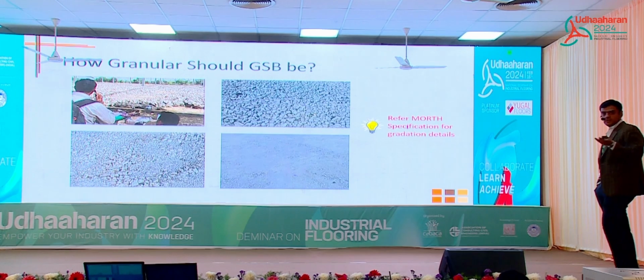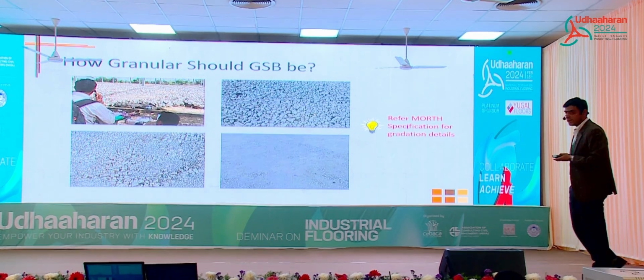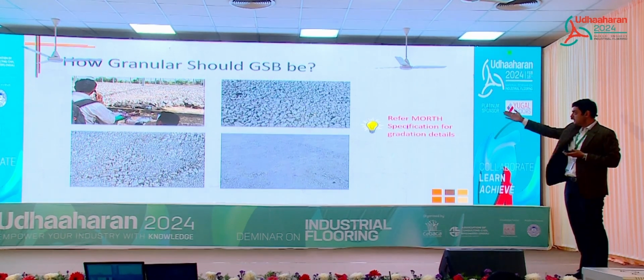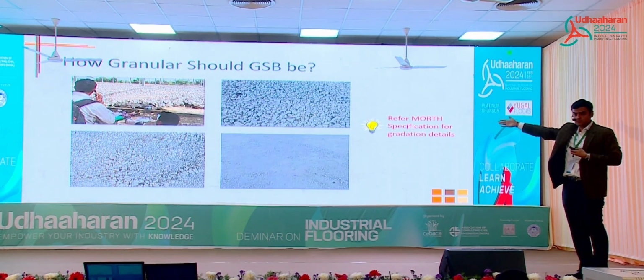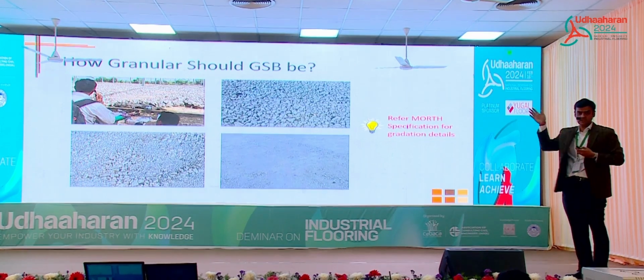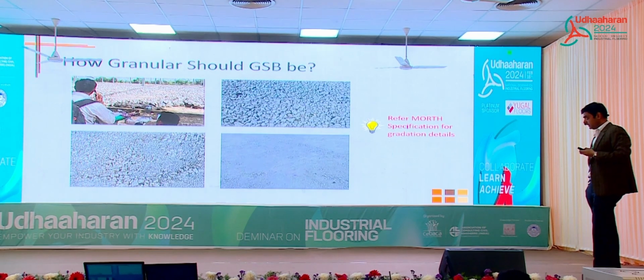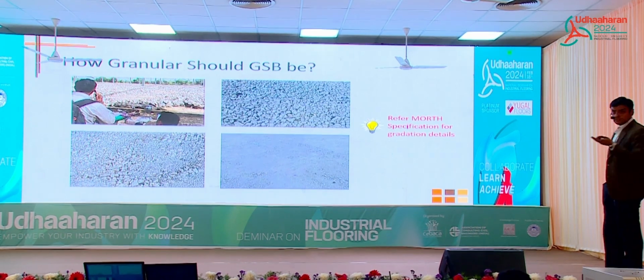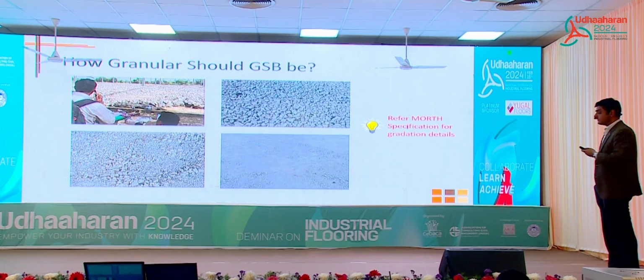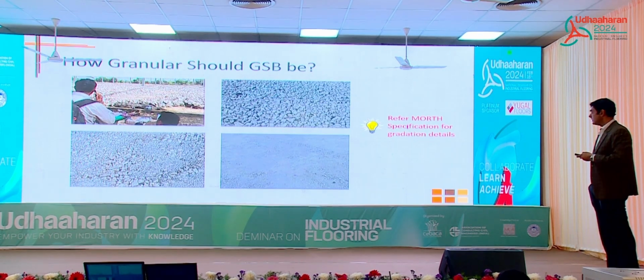Okay, so I'll leave this to you to answer: how granular should the subbase be? The first picture is clearly crazy. I don't know how they will be able to fill the voids. These are actually pictures I've taken from sites I have been to. Nothing in this presentation, by the way, is from the internet. It's all pictures of our work and sites I've been to. As sir mentioned, you can refer to MoRTH specifications for gradation.